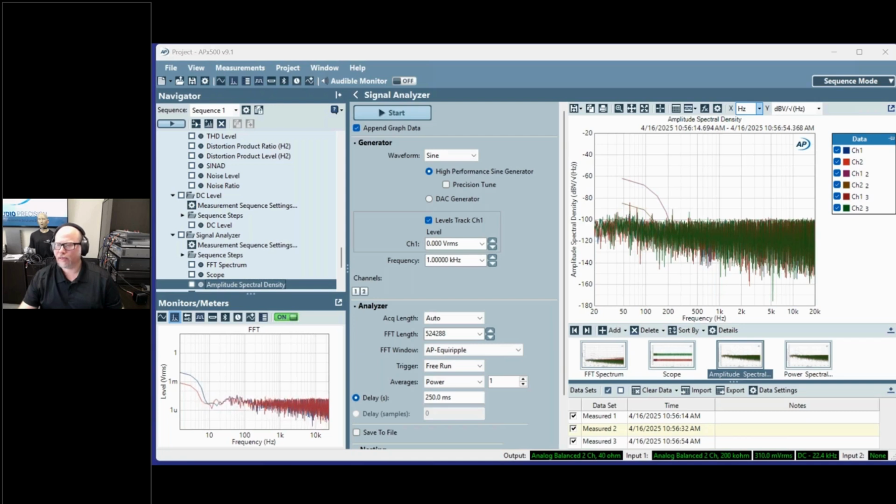You do not need a 517B to test power amplifiers. It's not a safety issue. A 517 is actually probably not the most appropriate choice for testing power amplifiers. Fundamentally, any of our analyzers can be used to test power amplifiers. You're just going to want to look at the input and output specifications for the analyzer to make sure that they're a fit for your amplifier under test.